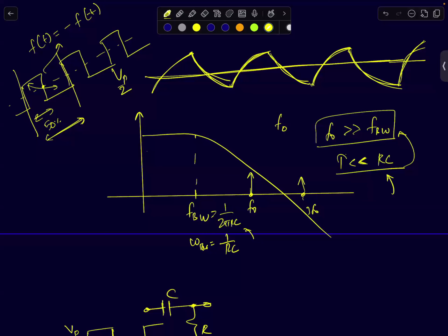On frequency domain, it looks like this. Can you tell me, if you look at this graph, at frequencies much greater than f bandwidth, what shape does this resemble? What does this shape remind you of? It's falling off at some rate, at 20 decibels per decade. We have seen integrators, differentiators. Does it remind you of something? The transfer function in this region?